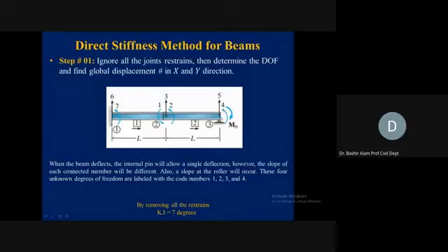Then we come to the restrained ones. The vertical displacement at joint 3 is 5, and then we come here to 6 and then 7. Why 7 degrees? The 7th degree arises because of this pin condition, which gives one extra indeterminacy. Kinematically, although it has 3 nodes, it is not 3 times 2, it is 3 times 2 plus 1 for this additional condition because of the pin. That is why it is a 7 degrees kinematically indeterminate problem.